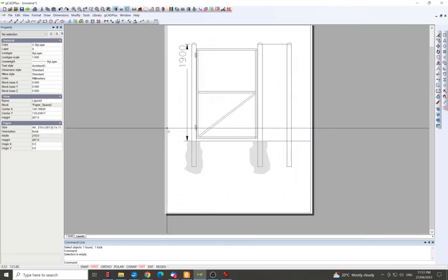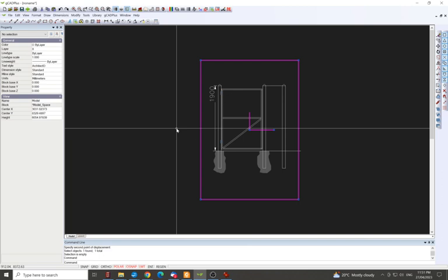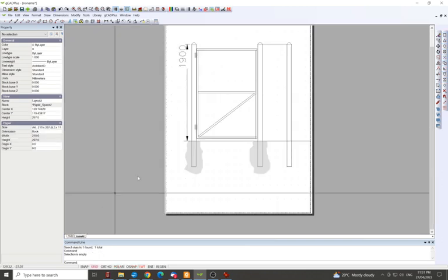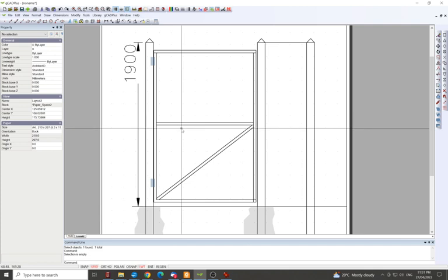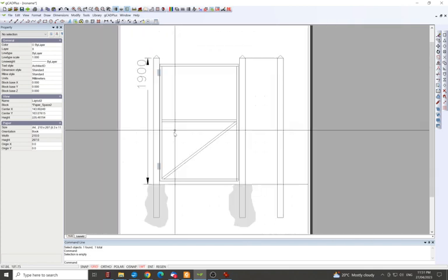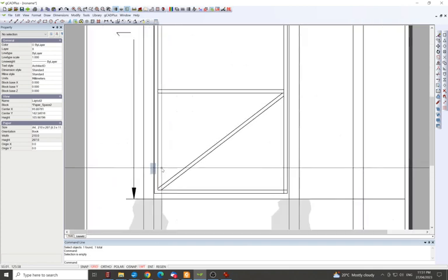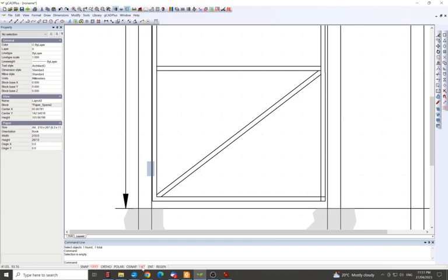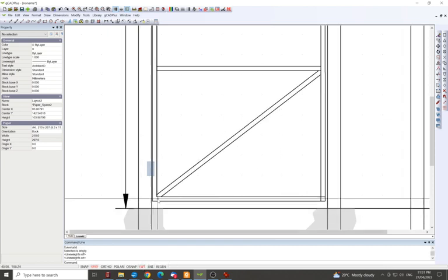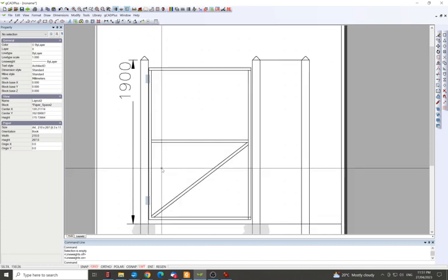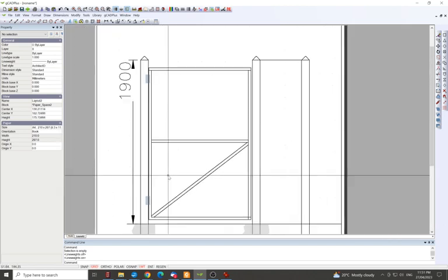And then to get back on it later, you can double click again and go back, and then click back to the layout, see it's serrated, double click and you lock it in again. But yeah, you can see this is coming together pretty well. The line weights are on. We turn that off, let's have a look at it. That's with no line weights. Depending what you're drafting, line weights are good or bad. It just depends how the drawing is looking. This drawing looks pretty good with the line weights on high because they stand out more.